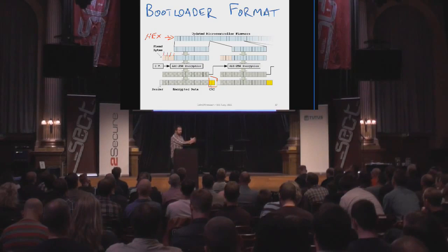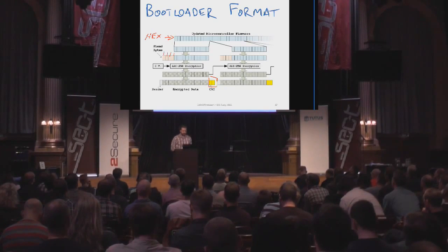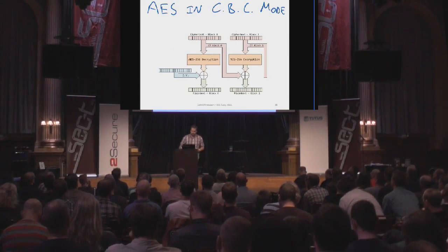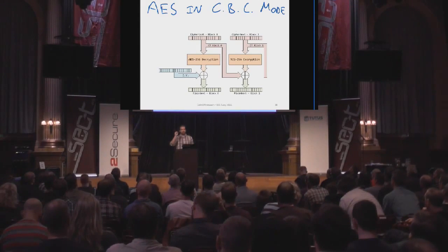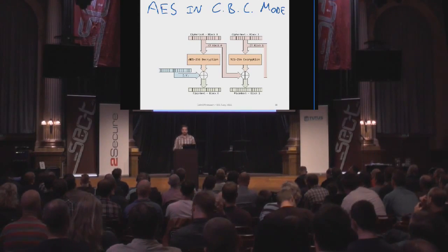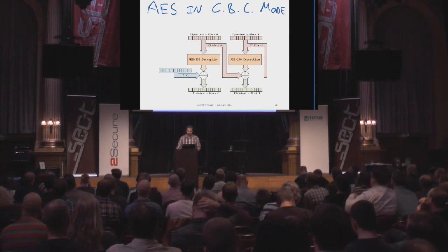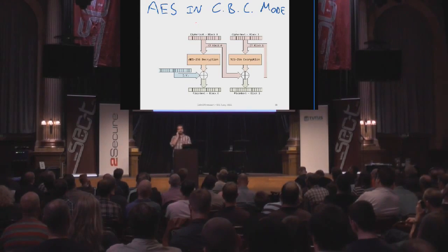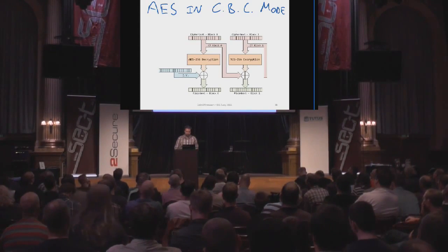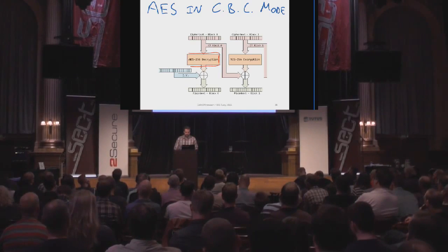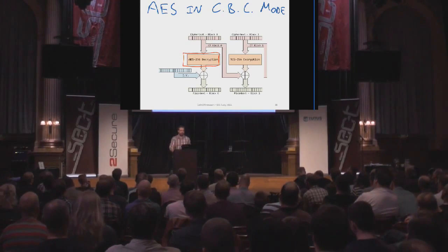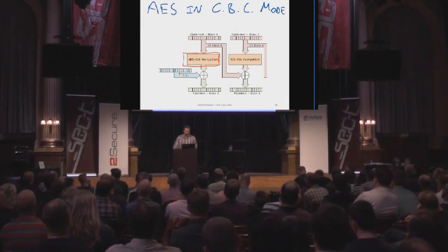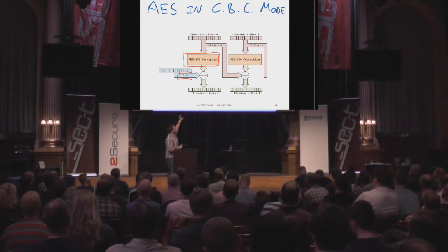To break this, you would physically need the device because that's the device with the encryption key in it. And all I would do is send it a bunch of random binaries. In fact, you could synchronize on how many decryptions it does in a large file. In my case, I just send it the first block, let it decrypt, and then reset it. Our objective is two things. We want to recover the key used in the AES 256 decryption, and we want to recover the initialization vector used as part of CBC mode.